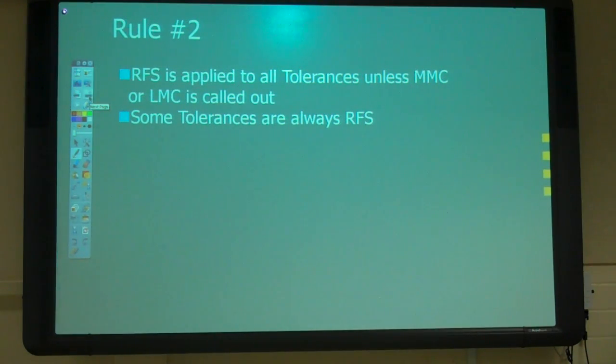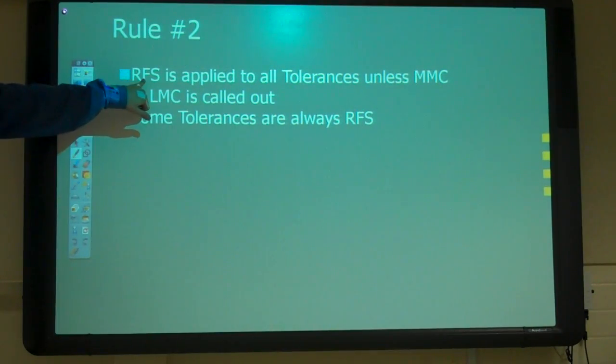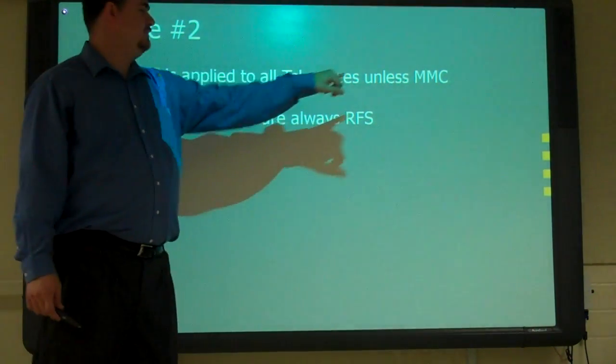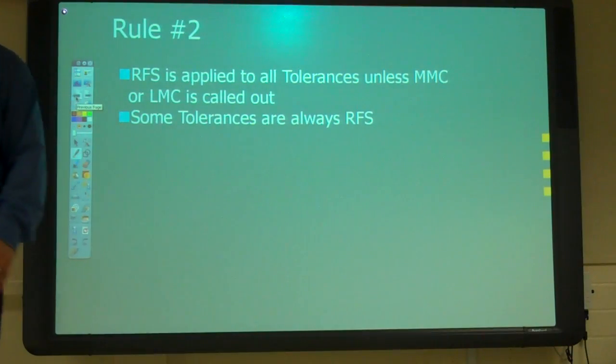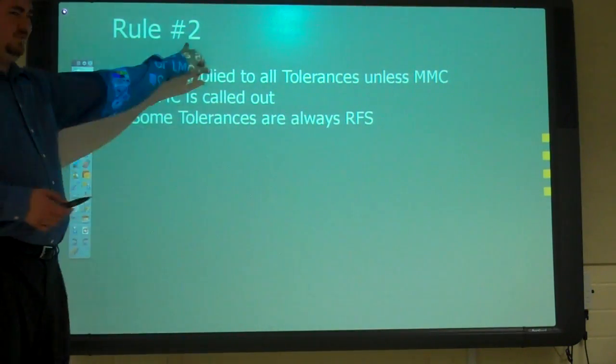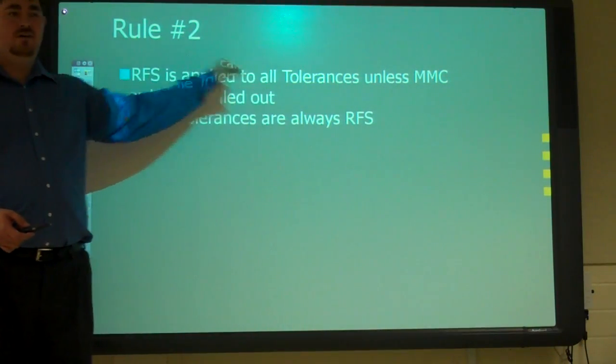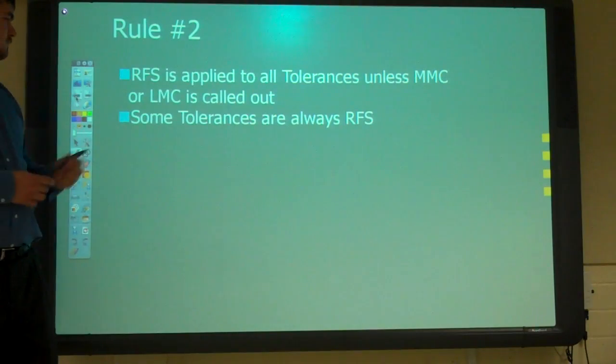I would think legally you would want it there, because somebody could always come back at you and say, wait a second. No, because rule number 2 is RFS is always applied unless MMC or LMC is called out. This is what takes care of that. This is why we don't show it, because unless you call it LMC or MMC, it's RFS.